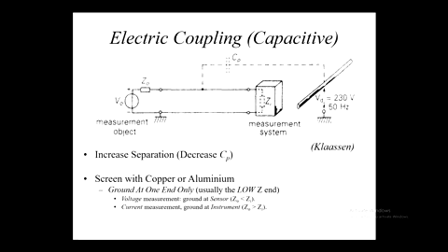Now, obviously the capacitance will decrease if we increase the distance away of this, because we're separating the notional plates of the capacitor. Now, we imagine this coupling to be a capacitor, dielectric being air, principally, and capacitance is inversely proportional to plate separation. So if we separate the notional plates, then the capacitive coupling becomes less, and we get less interference put in.